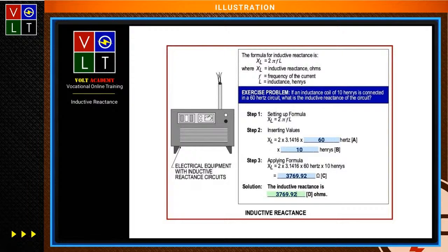So absolutely, when you're looking at that, basically what that means is: what is the effect of inductance on an AC circuit? Well, that's going to be called inductive reactance, because it impedes the flow of what? Current in the circuit. Yep. Now, when I look at the inductive reactance here in the AC circuit, what is it? It's proportional to what? The inductance and the frequency.